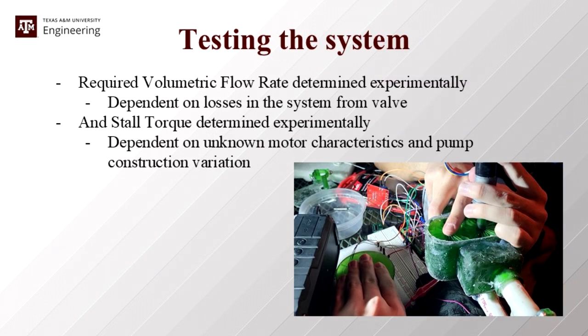In practice, the system works by using the gear pumps to force a difference in water level between the two containers, measured by the weight of the desired container. Our system has a leak valve, which tries to bring the system back into equilibrium from the level the pump forced the water to be.